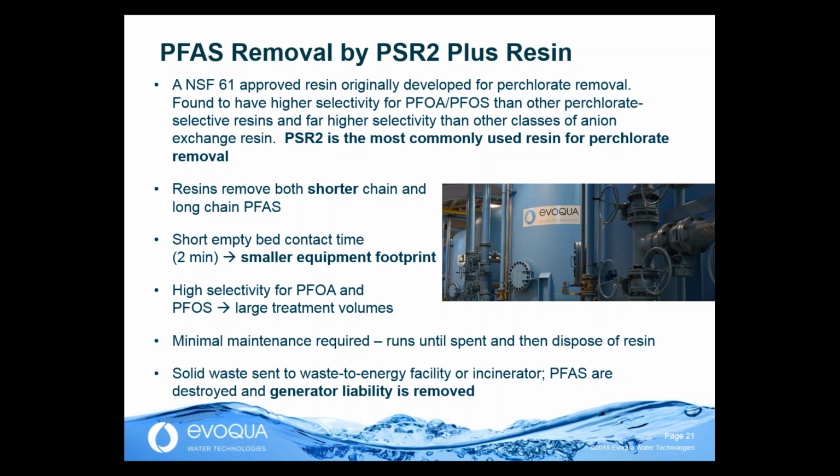Another nice thing about resin is it has a 2-minute empty bed contact time. Well, what does that mean? Sounds like just a bunch of acronyms that I'm throwing at you, the EBCT, but really what it means to you is that you can do treatment in a much smaller footprint.